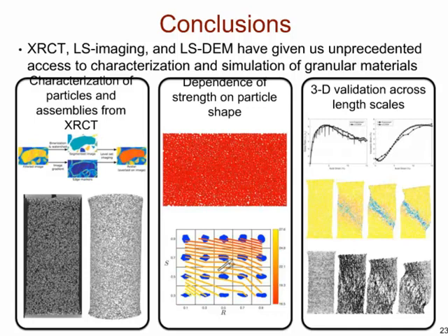And I'll just take the opportunity to mention that if there are no fines in that particular test that we call set imaging, we never have to use a scale to weigh the soil, and we never have to use an oven to dry the soil. And these tests are extremely quick. In fact, right now we're working on a project where we hope to run as many as 25 to 30 tests per day to characterize a riverbed over a distance of 7 miles.